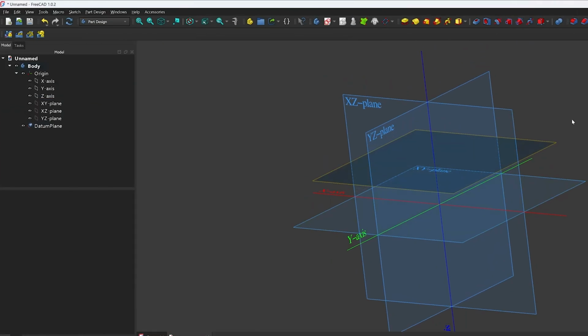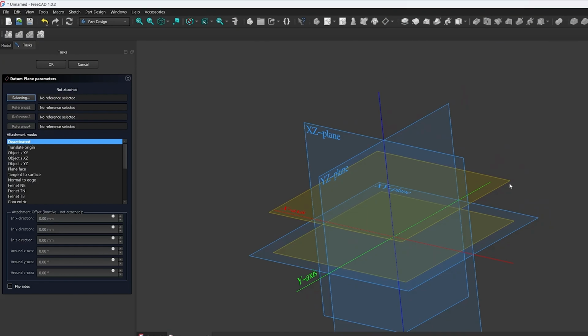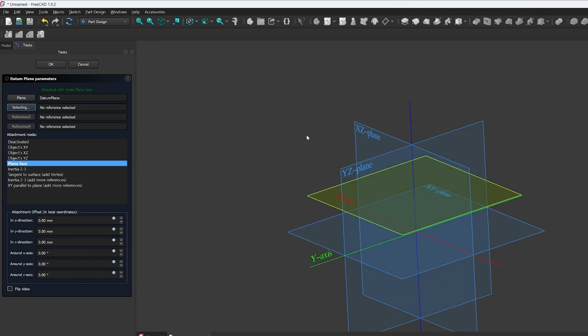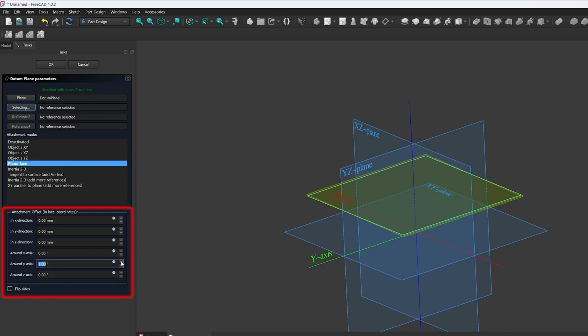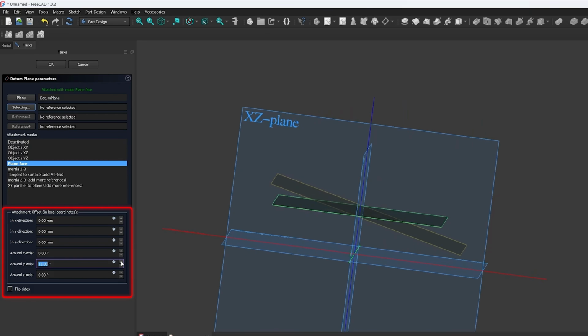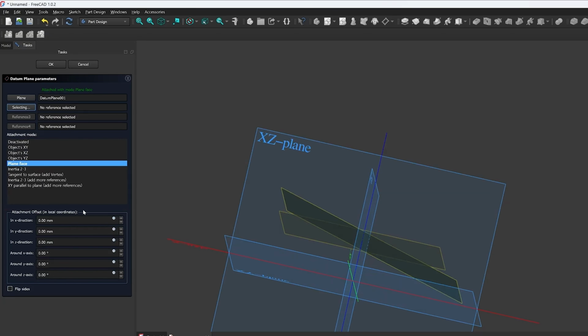Alright, so I have created one plane, and probably one plane won't be enough. Let me create another plane. And this time again, I'm going to select this offset plane, and instead of making another offset, I would like to make some adjustment in angle. And as you can see the preview of it, this new plane is, let's say, a 15-degree angle, and this time I'm going to choose this angled plane as a reference.